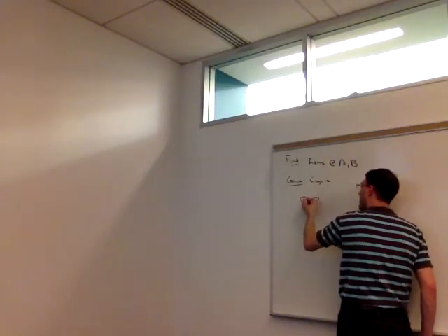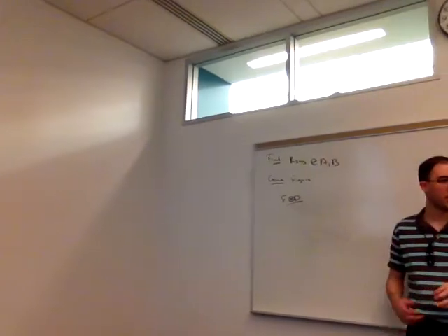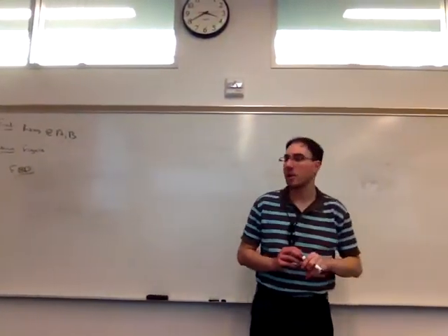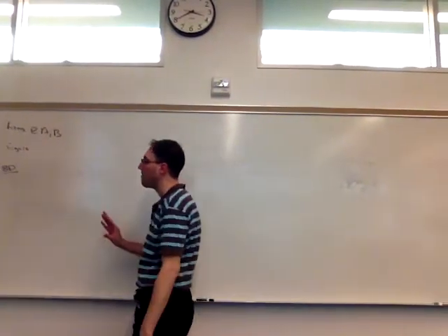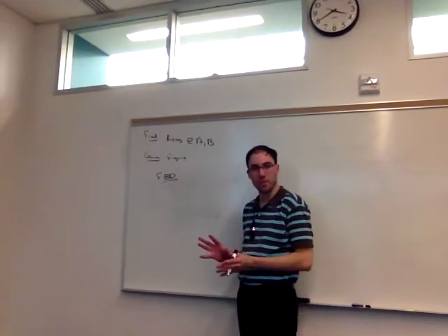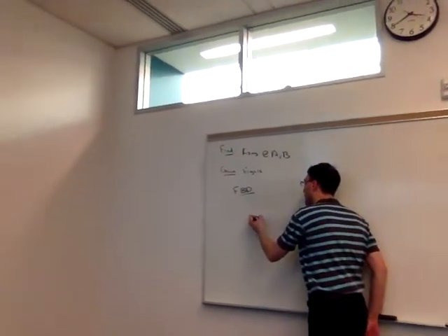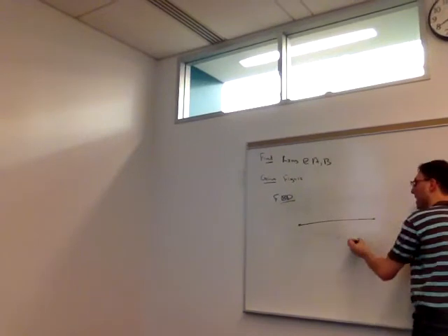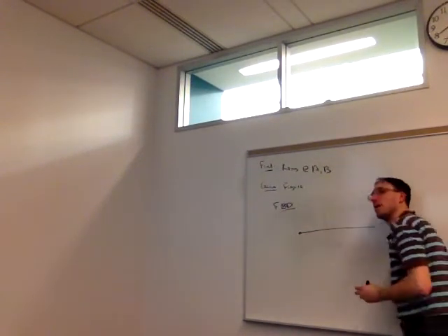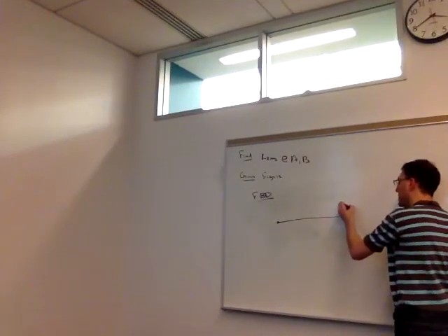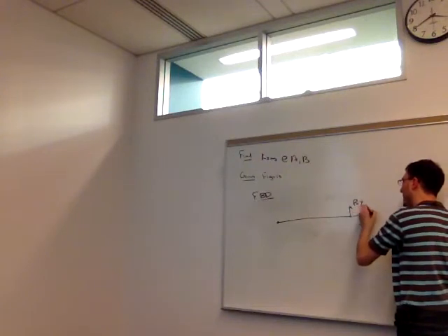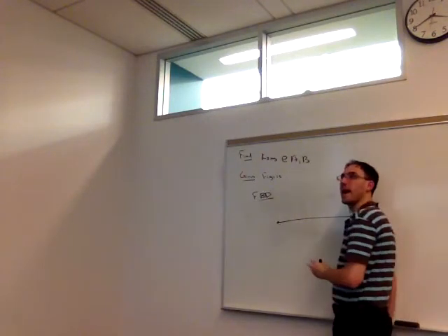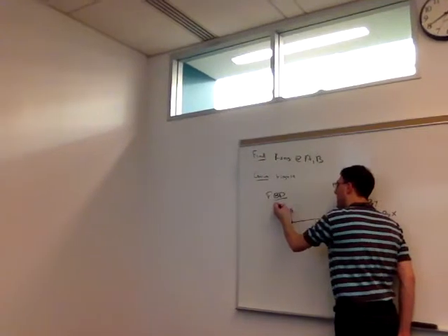We start in the same place that we always do for equilibrium problems. We're going to start with the free body diagram, and we're going to see how we model the system with the distributed load in our free body diagram. So I'm going to choose the beam as my object of interest. At B, I have a pin, so I model that just like I have in the past. At A, I have a roller.